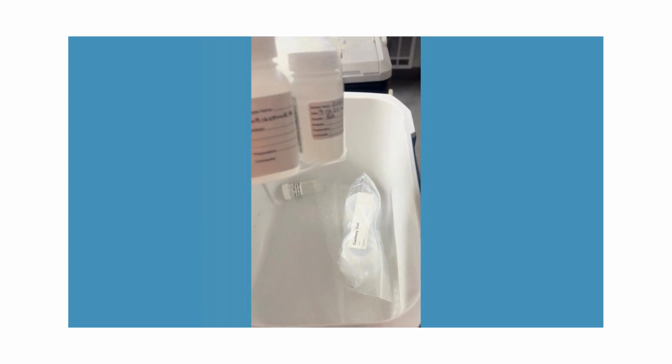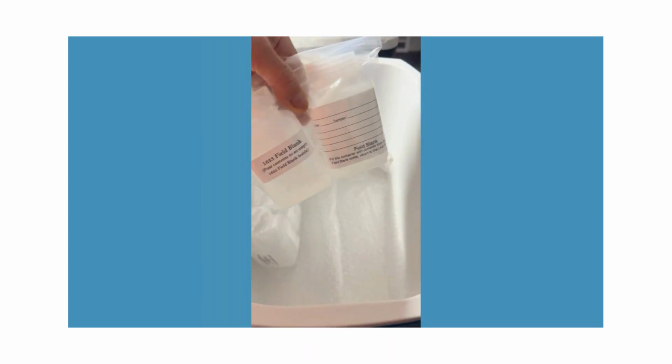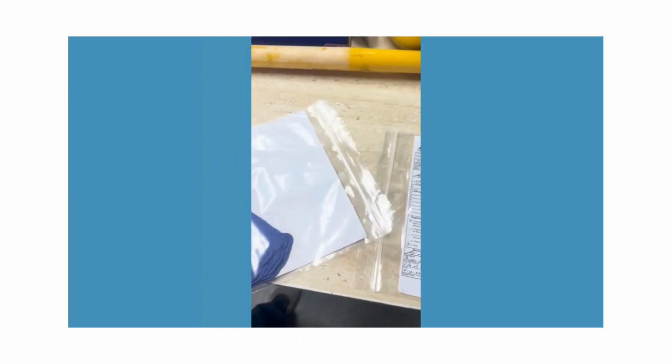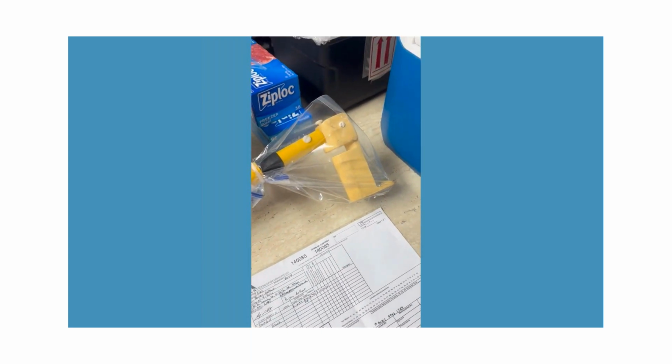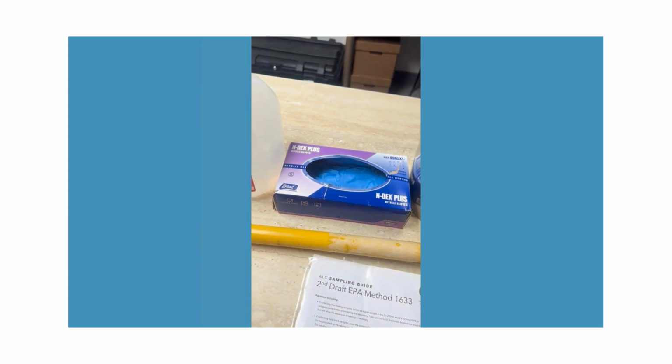Our sample bottles have been filled out, ready for collection. And this is the field blank, which I haven't taken out of the package yet. I will transfer this out in the field into the sample bottle when I'm collecting my samples. This is all according to my contract lab's directions. They also send with the directions a set of gloves, which I will start with, since that's the materials that came from the lab. My dipper has been decontaminated and sealed up. All my other sampling equipment and my biosolids equipment have been decontaminated. Got my gloves and my water.